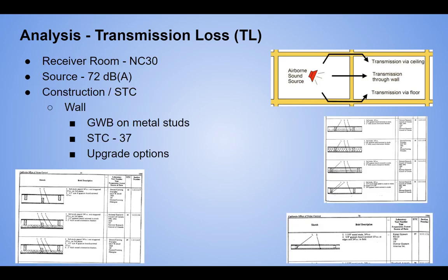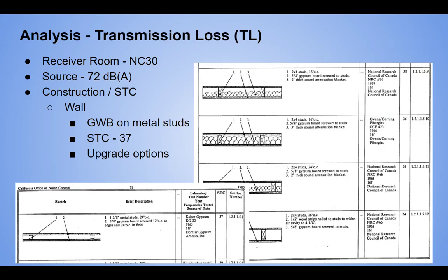We've got some different options that we can look at. We can stay with the same type of construction, and we're going to look at some types and why. You might be asking yourself, this 24-inch on center, smaller studs, why are we using that? Because if we look at 16 inches on center with bad insulation, so 2x4 studs, 16 inches on center with 5/8 inch gypsum on each side, we're still only at a 38, so we're not even where we need to be.